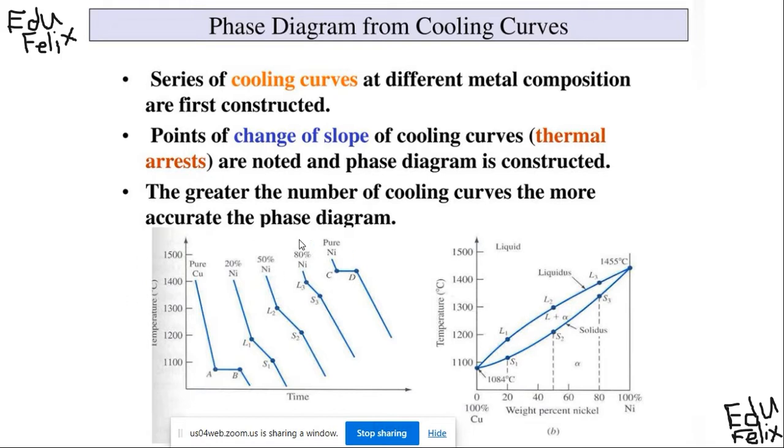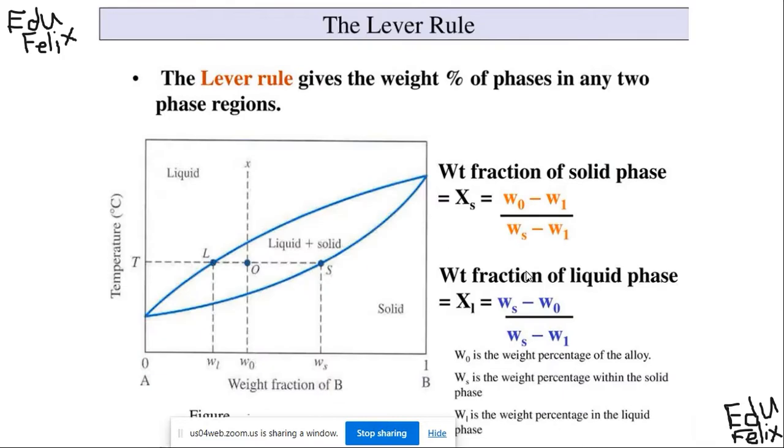So using your cooling curve, that means if you change your chemical composition and do this kind of test, you can construct this phase diagram. This is a binary phase diagram. Right now I think you can identify this is one of the primary phase diagrams, and here you have a solid phase and a liquid phase. This is a solid and liquid phase system, right?